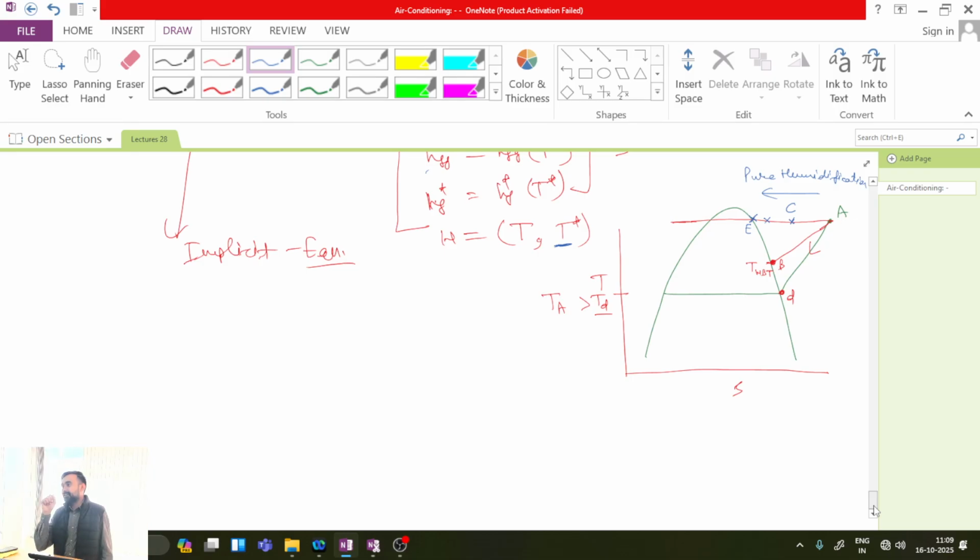So first point is, thermodynamically we know that for representing the thermodynamic state of the moist air on a property diagram, which I just now told, the psychrometric chart, I require how many independent properties? 3 independent properties. So it means for this room, first experimentally I must be able to calculate the 3 properties.